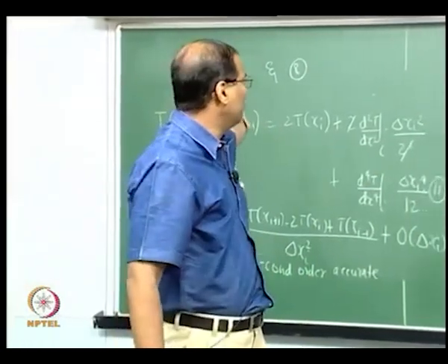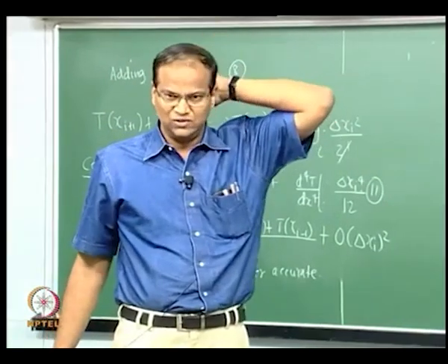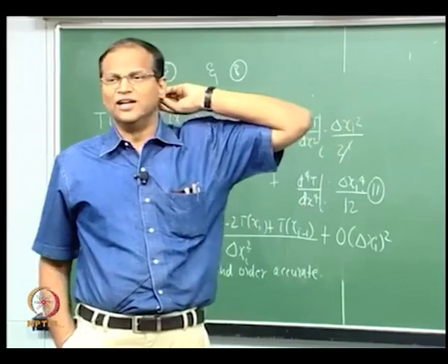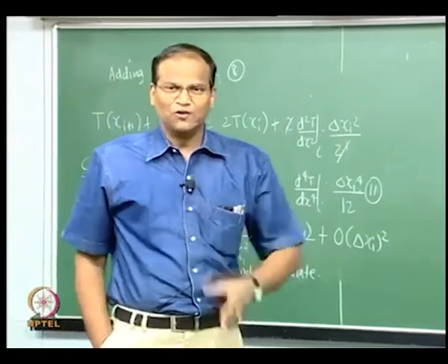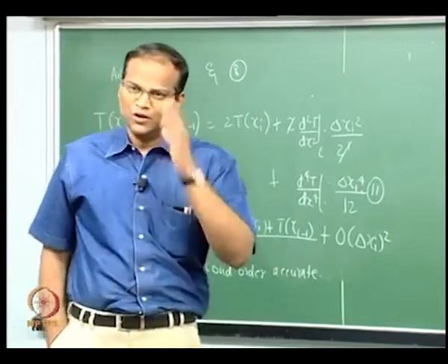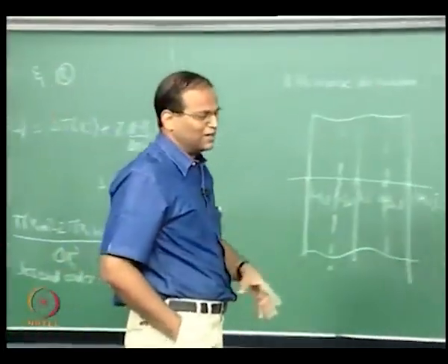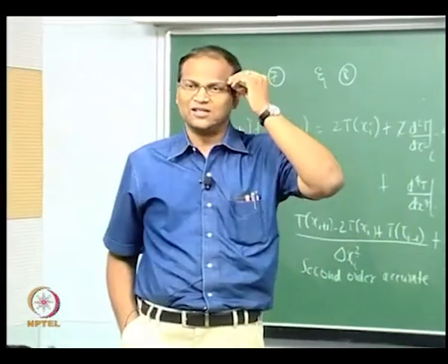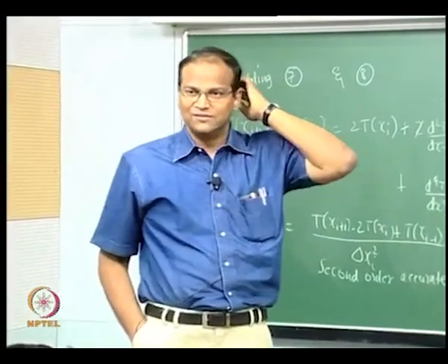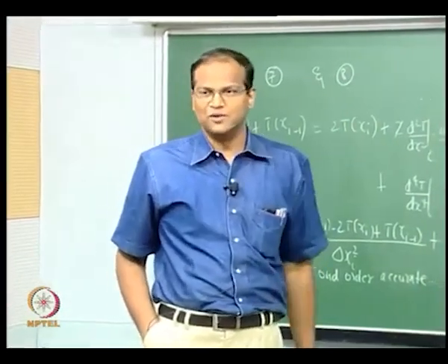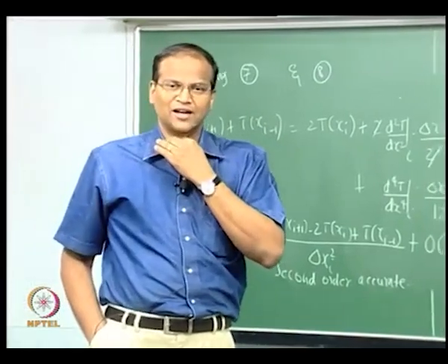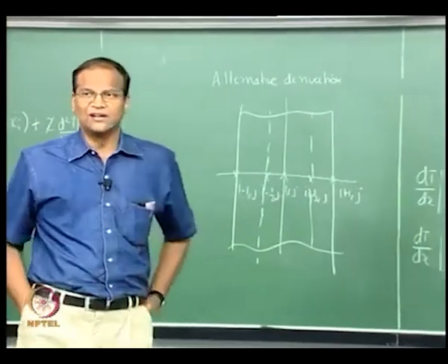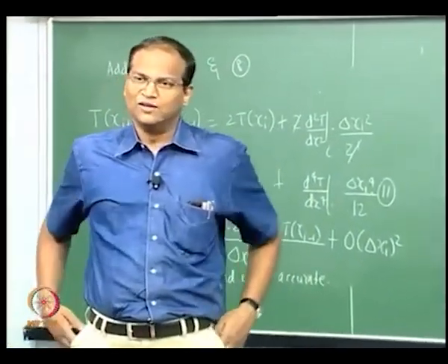That linear combination stems from the fact that you can express everything in the form of a Taylor series. So the goal of the finite difference method is finally to use all the methods you have learnt in linear algebra to solve a system of equations. Therefore, if you have to be good in finite difference and finite volume, you have to be good in linear algebra: how to invert a matrix, whether it is worth inverting a matrix more than 100 by 100, how to accelerate the convergence of Gauss-Seidel, what is successive over relaxation, under relaxation, for steady and unsteady what is the time step you have to use, cell Fourier number, grid Fourier number, unconditionally stable, conditionally stable, explicit method, implicit method, semi implicit and explicit, Crank-Nicholson method and so on. So you have to be good in all this, okay.